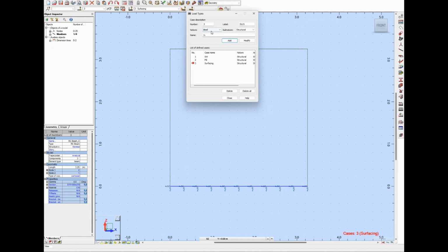So we also have our live load. So we just need to change our drop down menu to live. Make sure you go from dead to live, okay? We have our horizontal live loads, so our surcharges on the side walls. So we have it on the left hand side and then we have it on the right hand side. Finally, we just go back to dead and we'll pop in some fill, some horizontal fill.